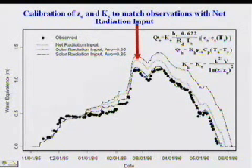We looked at the processes that we knew affected certain parts of the modeling process and adjusted the parameters pertinent to that. So for calibrating the surface roughness and the surface conductance parameter, those parameters play a role in the sensible and latent heat flux, which, if you have measured net radiation, you can't change the radiation at all.